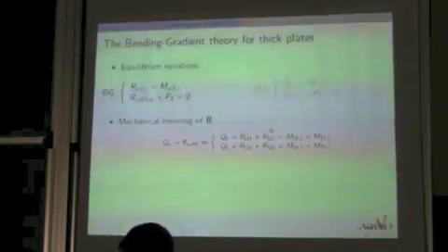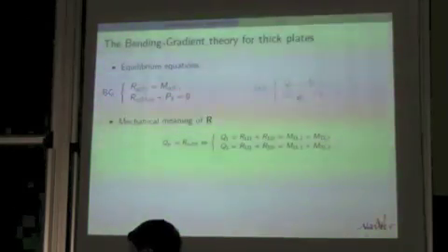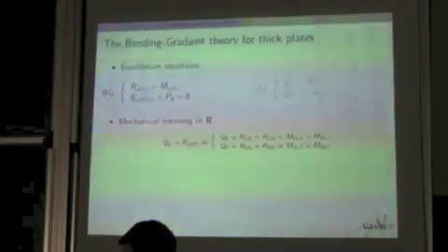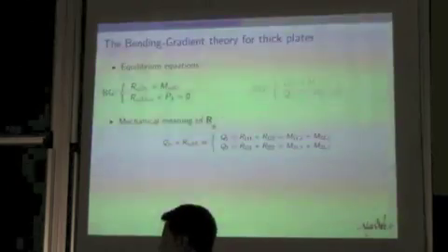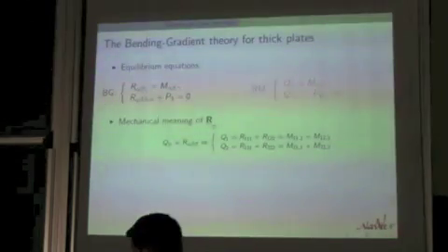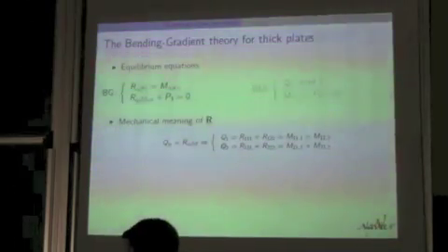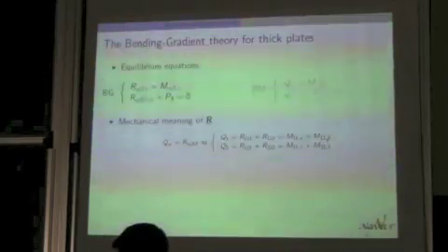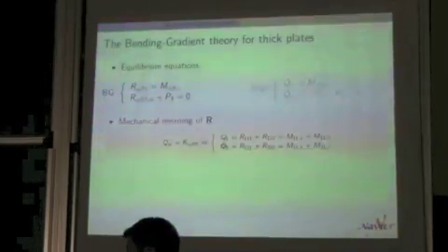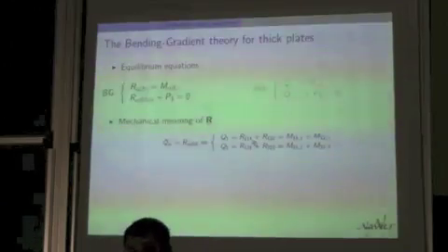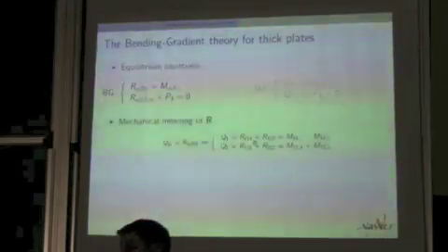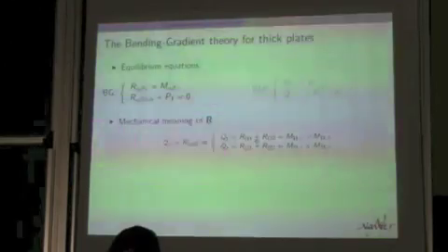And this is just the extension of, here you have the divergence of the shear forces. Here is just the same equation. And the mechanical meaning of R is just that instead of mixing different components of the gradient of the bending moment inside the shear forces, I make this distinction between them. Okay? And this is really important for heterogeneous plates.